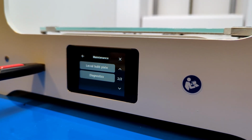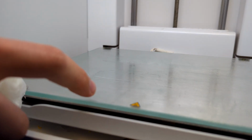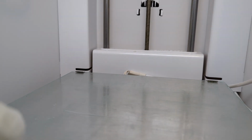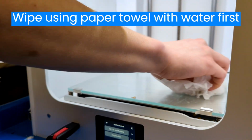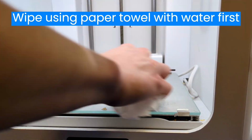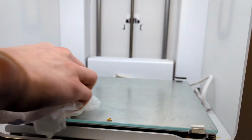And now before you do this, if the build plate is at all dirty, so here if you look at that, you can see there's a little bit of filament there, there's some glue, it's sticky, so we need to clean it. To clean it, you just need a paper towel with water and a dry paper towel. So just wipe it a bit until all the glue's gone. If there's still glue left, like you can sort of see there, there's glue there. It's not just water. So you gotta keep wiping until the glue's gone.